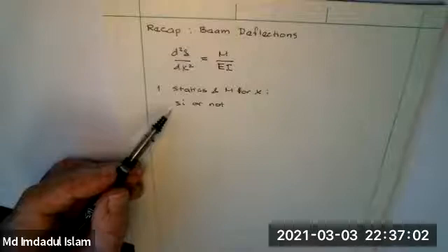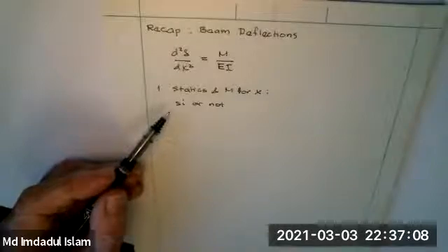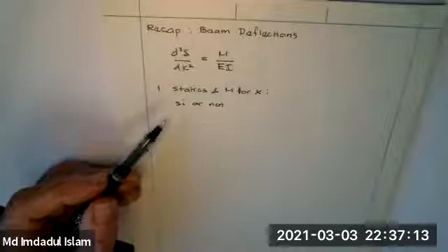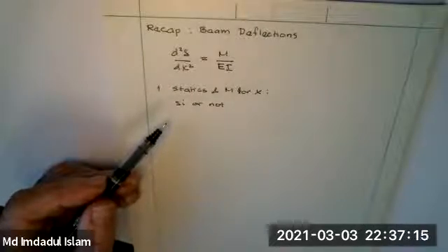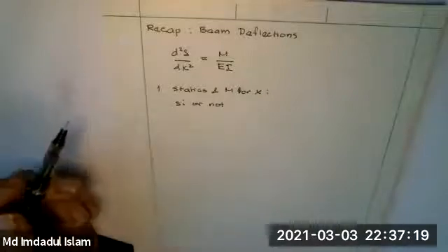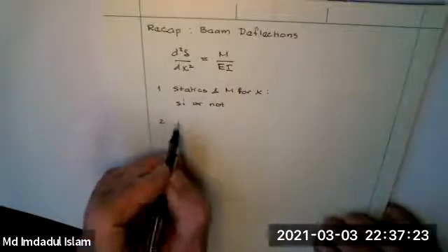Oftentimes, the force in the x direction is non-existent, so satisfaction of that condition is automatic. So you end up with 2 conditions. Then if you have 3 unknowns, it's statically indeterminate. If you have 5 unknowns, it's not only statically indeterminate with 1 unknown, it's got 3 extra unknowns. Okay. So you want to make that decision. That feeds into what you do next.